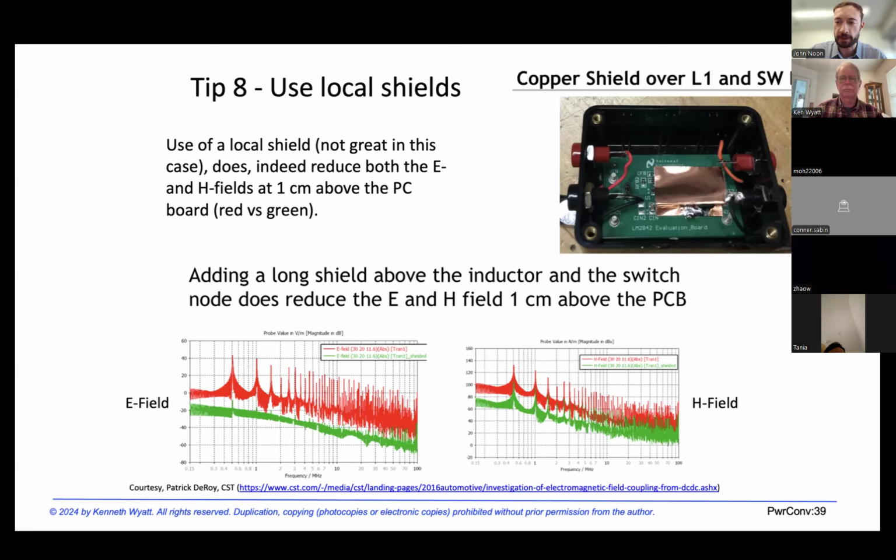Okay, thank you. So how important is splitting the signal ground and power ground? It looks like a big ground plane is sufficient since the high frequency noise signals will navigate themselves. I would not split power and signal ground. Now there's cases where you're using, yeah, let me go back to that slide.